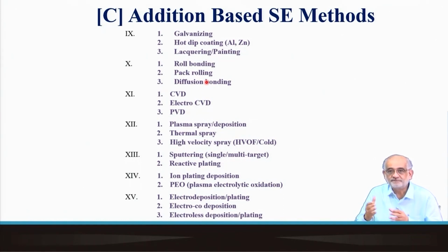it also protects from ingress of moisture or any other atmospheric influence that can degrade the taste and the contour of the chocolate. So those are created by a special process where the aluminum foil, starting from a millimeter or less, is brought to a level of a micrometer or somewhere around that. So you can very well imagine that 3 orders of magnitude reduction in thickness dimension. And in fact, at that small thickness, the foil appears like a paper, so you can easily tear them apart. Otherwise, if you try and do that with a millimeter thick aluminum sheet, you'll never be able to do that unless you are a Superman.